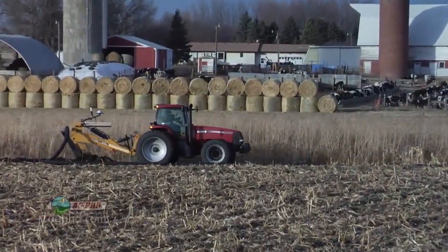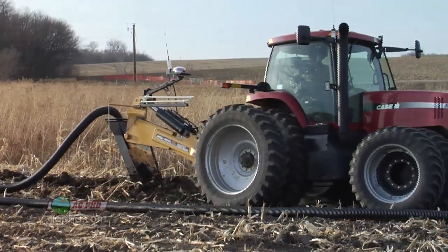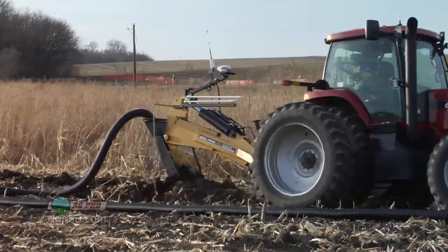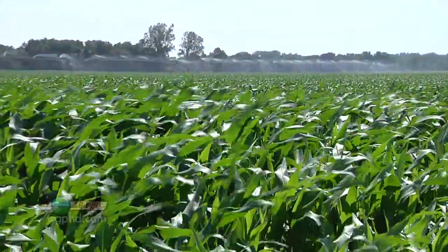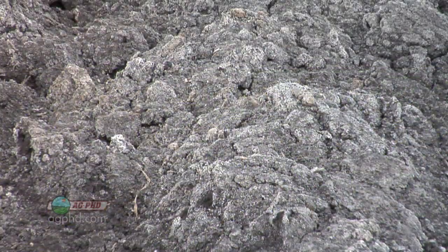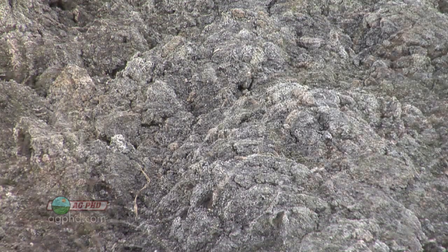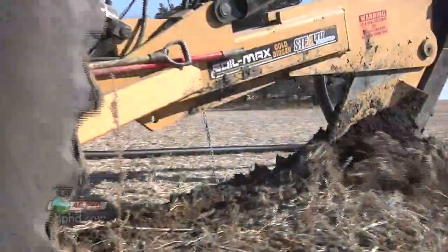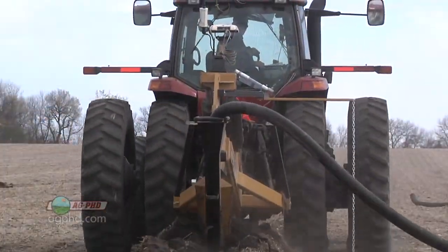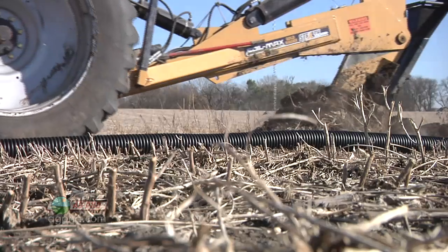For example, we've been in Arizona, and you would think, oh, in this super hot climate, they don't need drain tile there. Yeah, they do, because they have excess salt problems with their irrigation all the time. So they put the tile lines below ground, and they don't have nearly as much water issue as we might up here in the northern part of the country, but they have a salt issue. So they can get those salts flushing down through the tile line if they have some water moving through that soil. That's all it takes. You get tile out there, over time, you're going to fix your salt problem. We've seen salt levels typically go down 0.2 of a point per year in most soils.